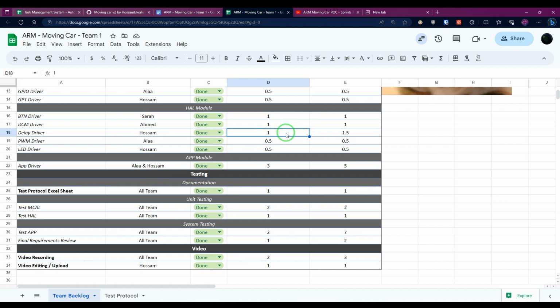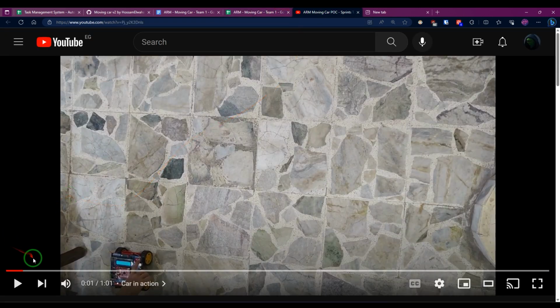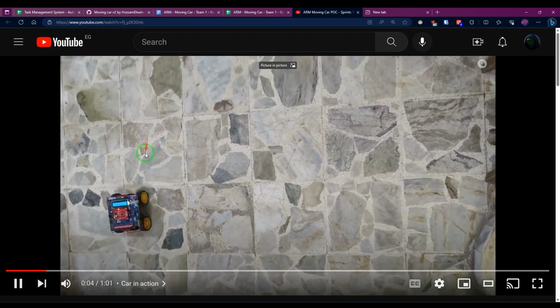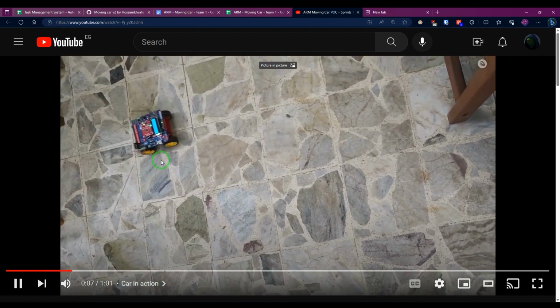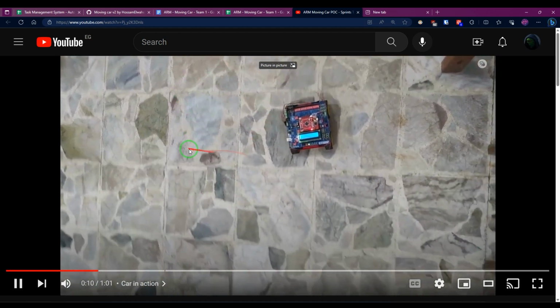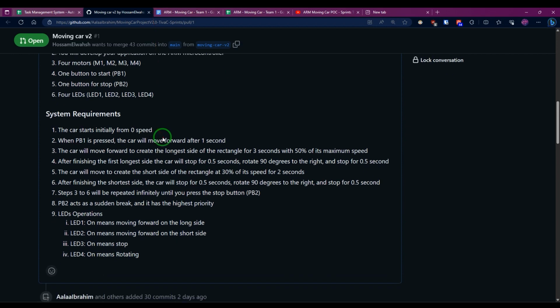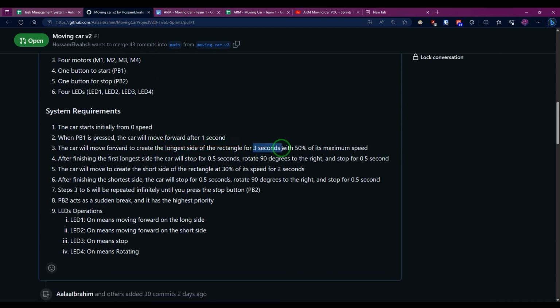there will always be some give or take errors because the battery voltage is not really stable, and also the ground friction is not always the same. If we used a gyroscope or something, we could make this much better, but using batteries, you can't really get a sharp 90 degrees rotation, but we made our best to finish this project.